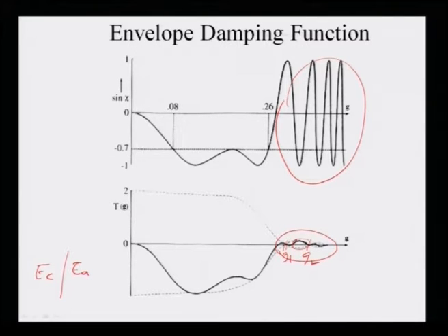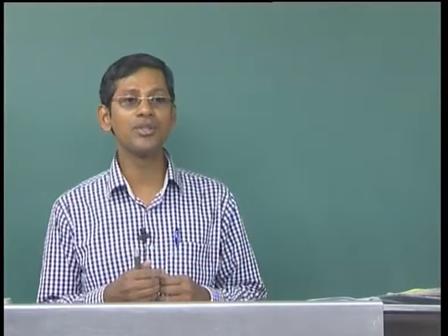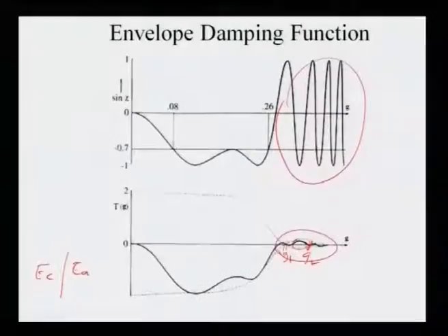That is why in many high resolution microscopic images nowadays, the resolution is about, say, 0.8 Angstrom for the Titan microscope or 0.5 Angstrom for the aberration corrected microscopes, but the information can actually be at picometer levels. So, we can achieve information at much higher resolution levels, much better values than the resolution given for the microscopes. That is what is possible in the microscope because of the presence of the small higher order g values in the transfer functions. So, these all give us some extra information.